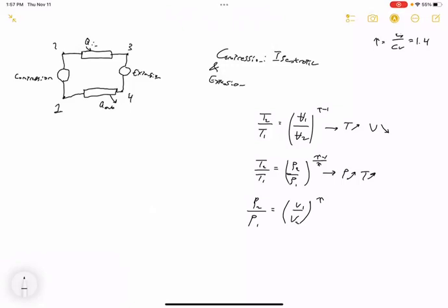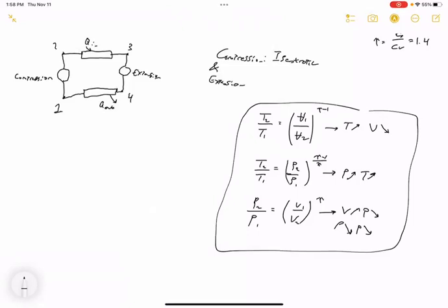So this is something we already knew, but it's again just saying that in the case of an isentropic process, it changes exactly according to this relationship. So of course, V goes up, P goes down. Or in other words, density goes down, pressure goes down, right? Because V is just 1 over rho. So these three relations are known as the isentropic relations.